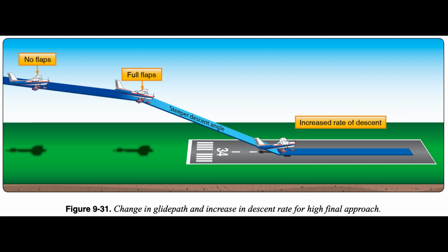Since a sink rate in excess of 800 to 1000 feet per minute (fpm) is considered excessive, either technique avoids the high sink rates that would occur if the pilot dives the airplane toward the aiming point. Since a high sink rate continued close to the surface makes it difficult to slow to a proper rate prior to ground contact, it is not a good idea to dive toward the aiming point.